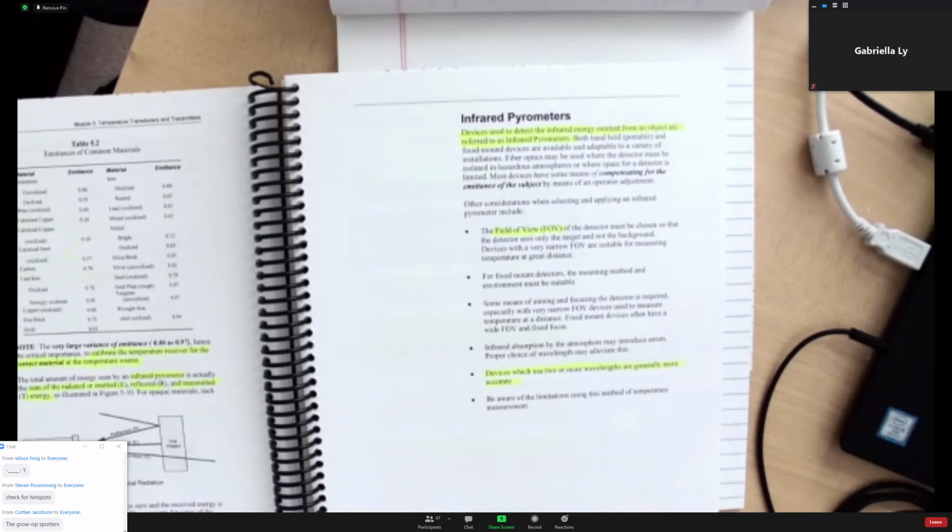If you don't do regular maintenance, tightening those connections or cleaning up, it could cause a high resistance contact, and when you draw large current, that becomes a hot spot,